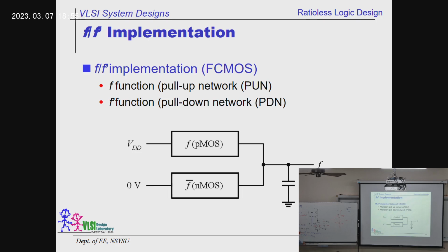However, if you see series, then you're in big trouble, because we would like to have the same rising time and falling time. But if we stack or serialize these two transistors, as I said yesterday, if you consider this equal to an R resistor, then you are going to have R and R, which is 2R, because they're in series. So the impedance in this path will be larger than the original one. We don't like that. We like to balance it, because the pull down is the same as the right-hand side.